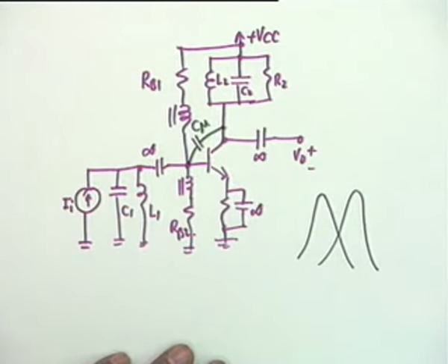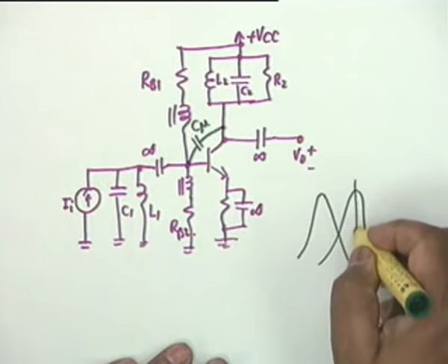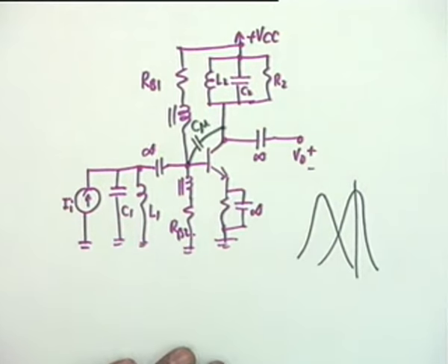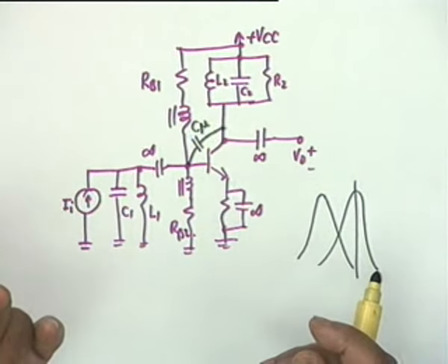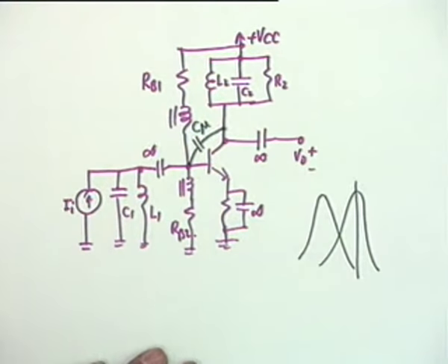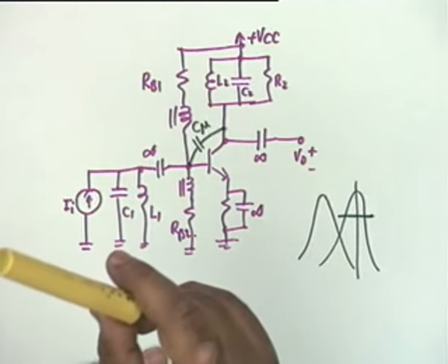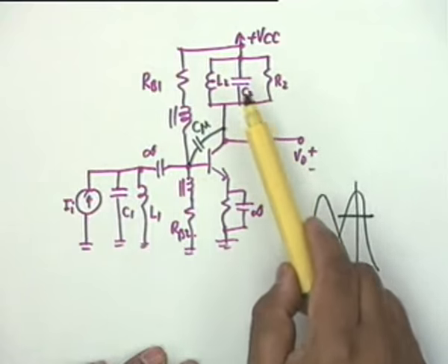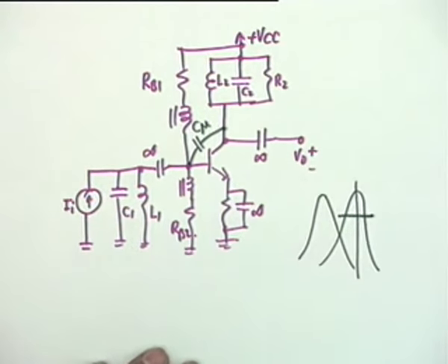Sir? Yes. But at the resonance frequency, the tuned circuit will have a pure resistance at the resonance frequency. Now it is not an oscillator circuit. We have to accept a band of frequencies, and therefore you can no longer consider this as a pure resistance. Okay, you have to consider around this frequency where L2, C2 both come into effect. I was expecting this question. While in an oscillator circuit, a single frequency oscillator, we could do that. We could take the resonance value, but not in a narrow band, not in a tuned amplifier, where there is a band of frequencies involved, so the reactances have also to be considered.